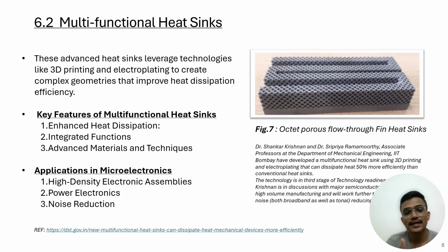So second comes the integrated functions. Here we can integrate different functions at the same time, like mechanical stability, noise reduction, and heat dissipation. Another feature is that advanced materials and techniques are used. So what are the applications? In high density electronic assemblies and high power electronics, where input output and pitch size is very low, we require very high speed and good signal integrity. So there we can use this kind of heat sinks, and also for noise reduction.